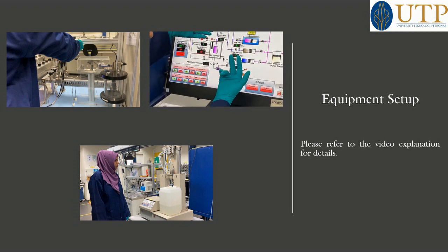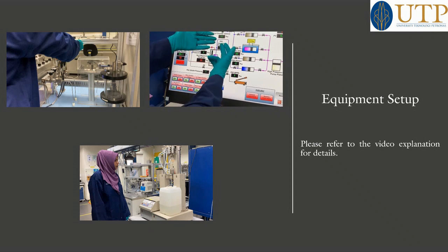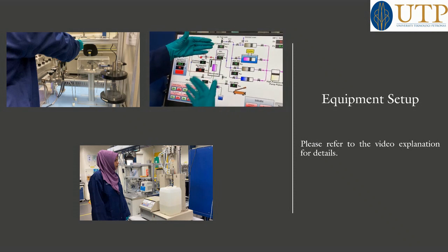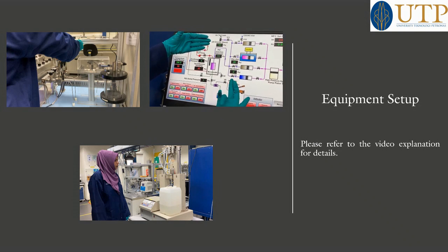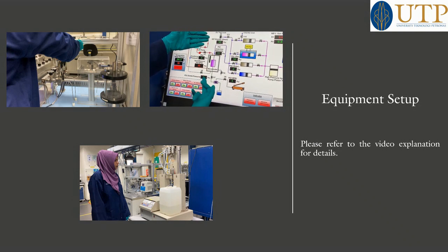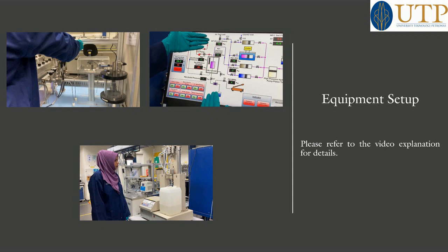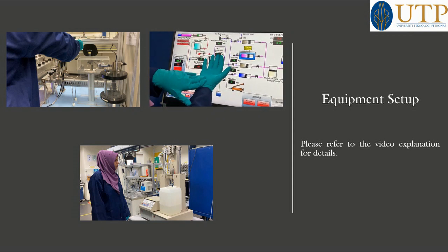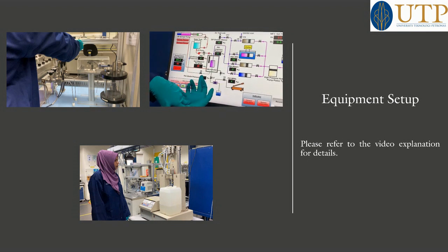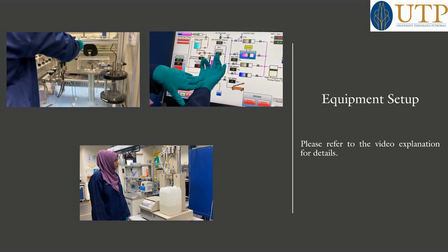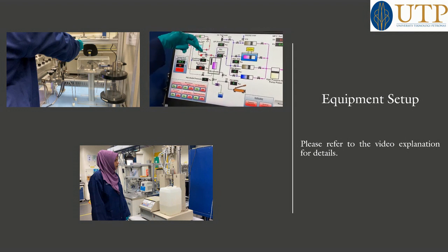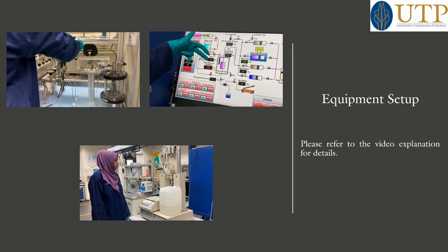Suppose my BPR is 500, so now my injection pressure will try to increase, and the outlet pressure is also high because of this BPR. It's like when the injection pressure is 11, my outlet is 1. When the injection pressure is 20, my outlet is 10. Like this, it will increase. So when it is 100, the confining pressure will be 140.